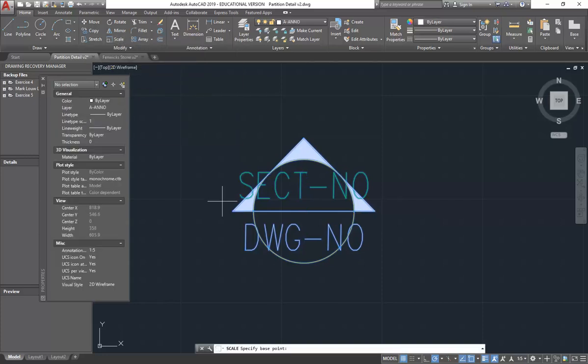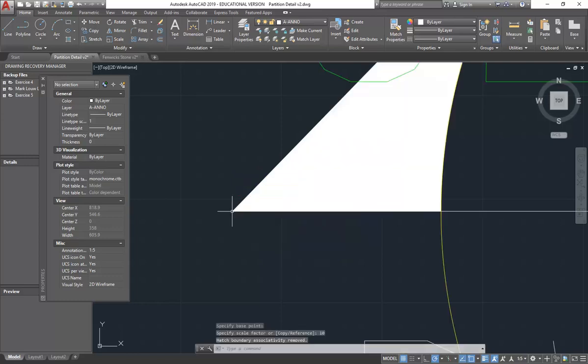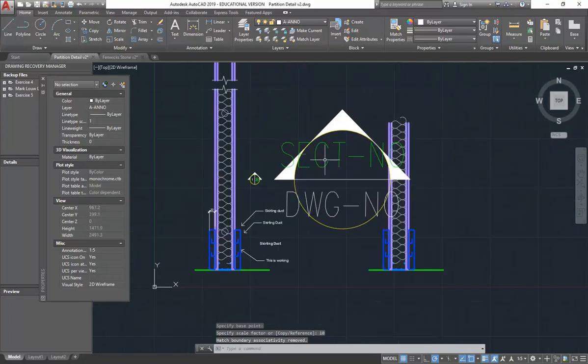So with the scale tool, I've got my thing selected, so I'm going to click there on the left. There's my base point. So it scales in that direction to the right. And then type in my scale factor. Anyone want to be brave and guess? Exactly, 10. Right, so I'm going to type 10, enter, and now everything is going to be 10 times bigger.